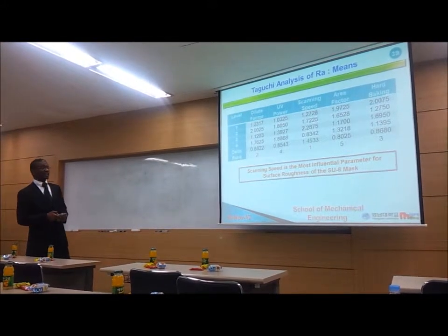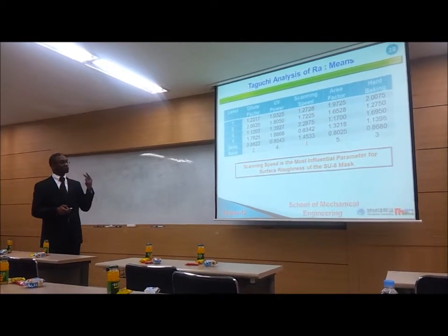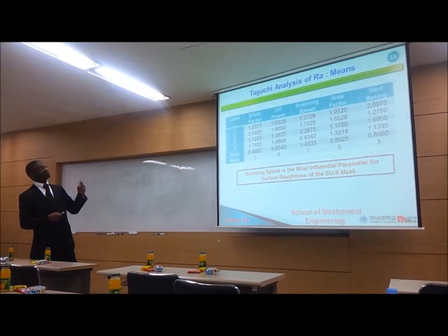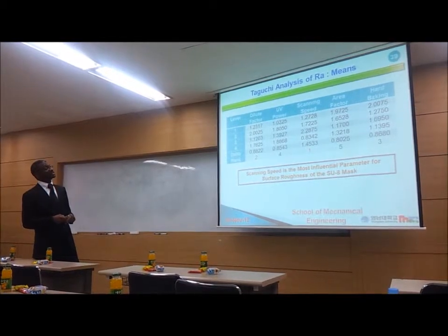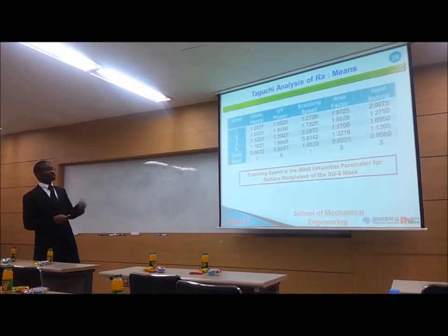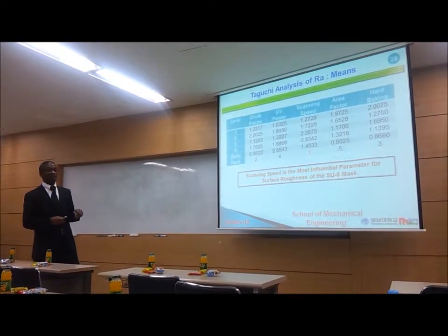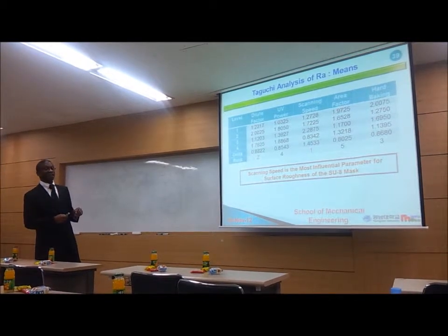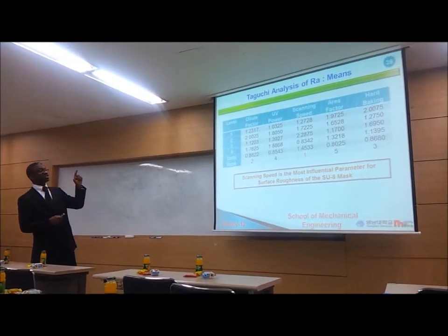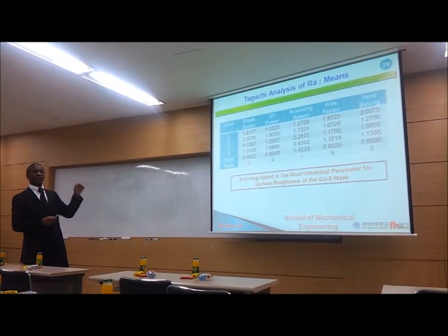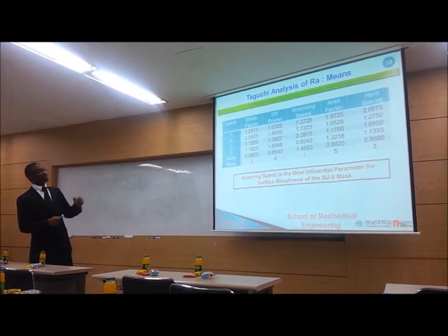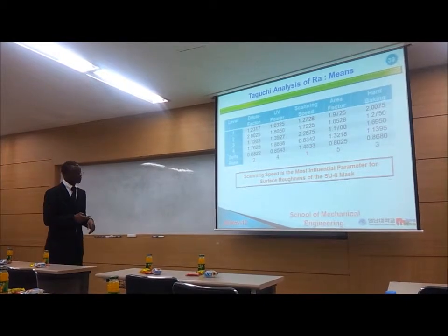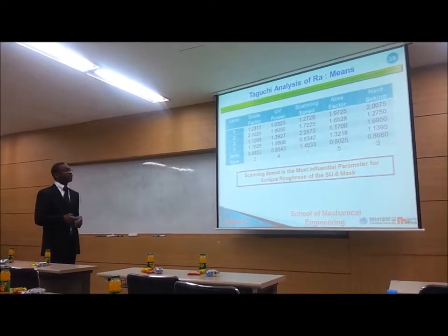Then I went to analyze again the surface roughness, because in my work I need to know the hardness of my mask and its surface roughness. Here there is physics in it. If you have the mask in a photoresist and you want to cut using abrasive gel, cutting a hard material with, for example, normal incidence, you can cut the hard material, but you will cut a lot of material from the workpiece, and you will also cut the photoresist. But if you increase the angle, you will cut the mask more than you are cutting the workpiece. That is the reason why we are trying to analyze those two parameters.